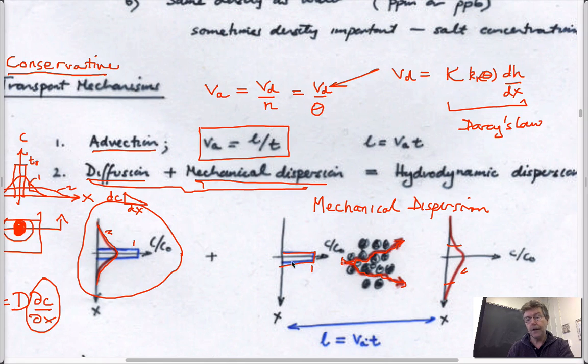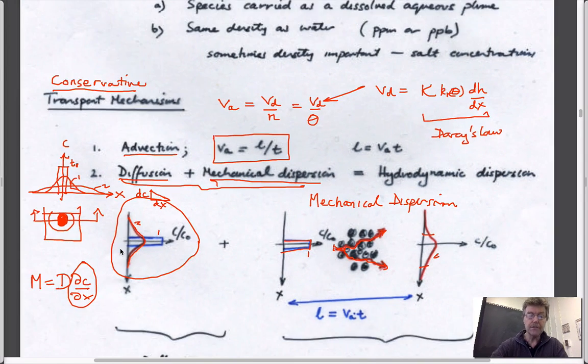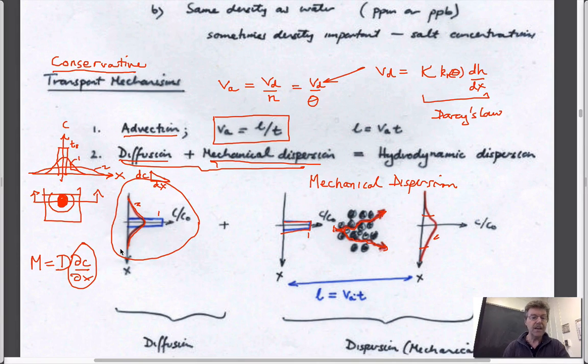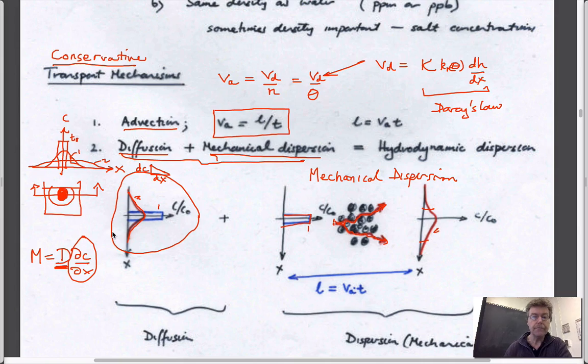If you're an observer going from upstream to downstream, then you see that the distribution is like this red line after some time, and it looks identical to the behavior of the diffusion. And so that's why we use it. So it turns out that we can think of mechanical dispersion and represent it by a diffusion-like process, which is Fick's law, which causes this behavior, even though it's nothing to do with it. So that's the rub.